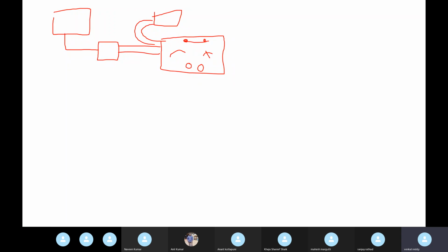So instead of other ECUs sending, we are using CANoe software. We will send CAN signals like a door signal, open door, closed door. Otherwise seat belt signal, not fastened or buckled, so the value changes.